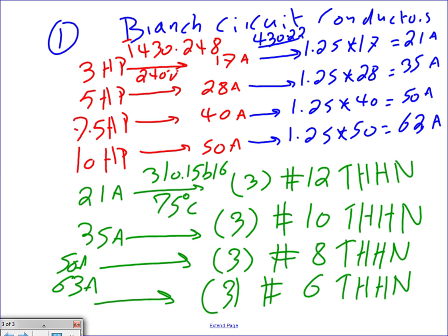All this stuff is to find the conductor size. Now, Ashley, you can go put them in a conduit and move on. If you decide to group them, we have to do the rating and size based on the rating. You might end up with a bigger conductor.